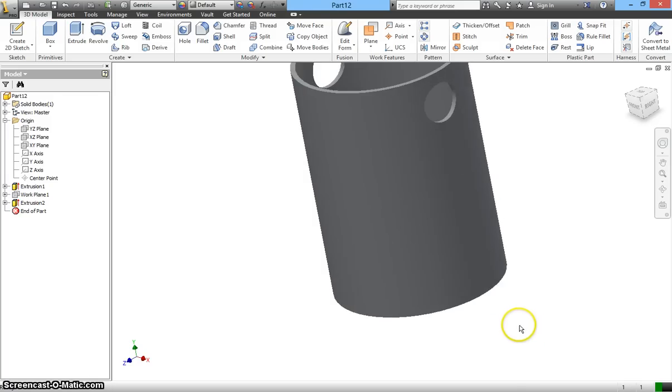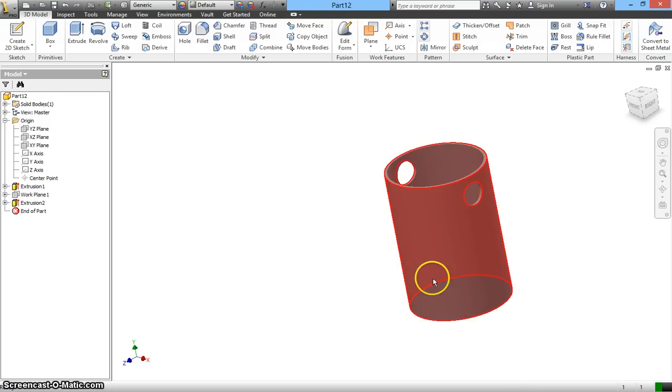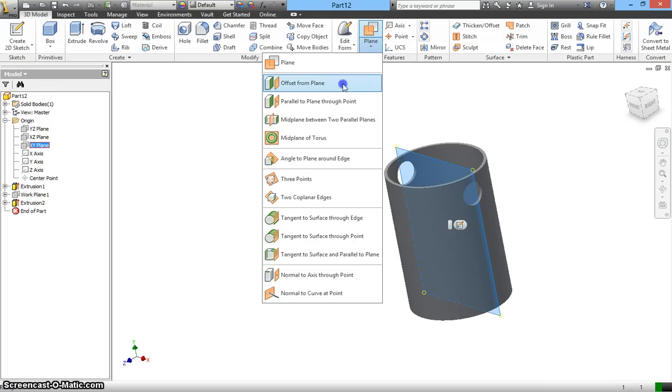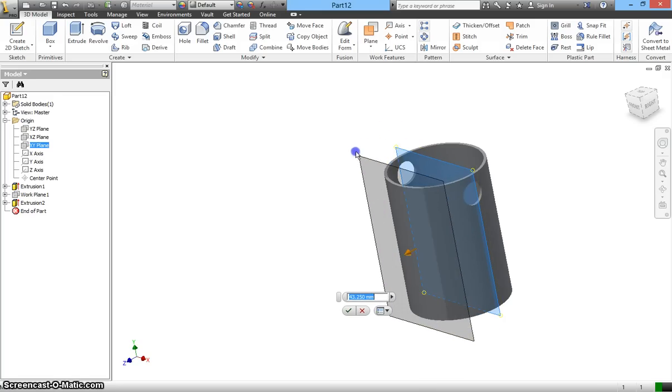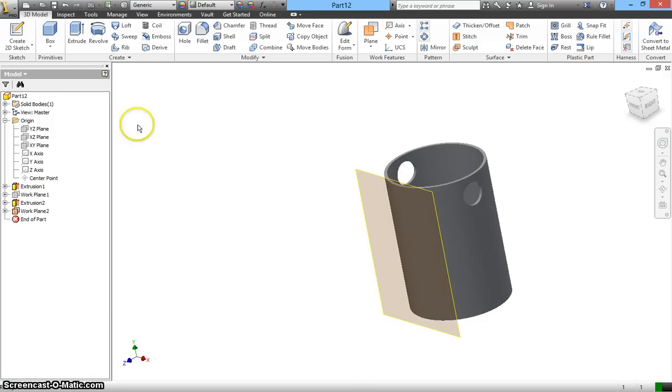The next step I'm going to do is draw a rectangular. I'm going to extrude cut a rectangular. Similarly, I'm going to choose a plane. I'm going to choose one of the vertical planes. And this time now I'm going to use the XY. I'm going to click on it, go to plane, drop down menu, select offset, and I see the gray thing. I drag it out until just nice. Okay, system puts 53. I'm going to put 55. Right, click OK, create 2D,